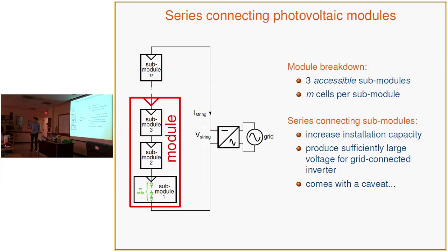So rather than increasing the capacity through increasing the string current, it'd be more beneficial to increase the voltage because you don't have as many losses in that central inverter. And also, going from an IGBT that's rated for several hundred volts to an IGBT that's rated for 1,000 volts, the increase in cost and size is marginal. So you have that other benefit as well.